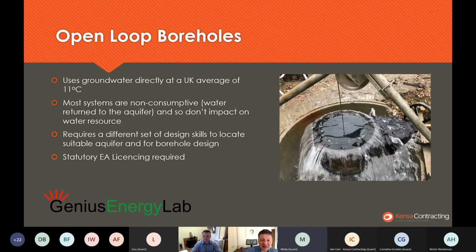And what you're effectively doing is you're creating in the ground a steel case down into the ground where your aquifer is. Your aquifer probably starts here, and we've got an open section, a casing here, which is exposed to the aquifer and allows water then to flow into the borehole. What we then do is we've got a pump suspended in the borehole here that then pumps up the pipe on which it's suspended out and into the plant room, and the water level will sit up in here.